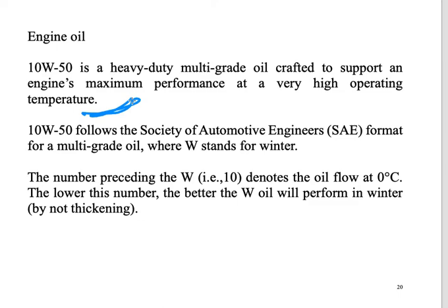10W50 follows the Society of Automotive Engineers SAE format for a multi-grade oil, where W stands for winter. So this is the idea. The idea of W is that when the temperature becomes lower, the viscosity becomes higher and higher, and in certain areas in the world, if you have a bad winter season, maybe the oil will become frozen inside your engine. So this means that it cannot flow anymore.